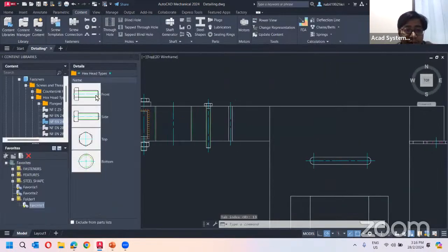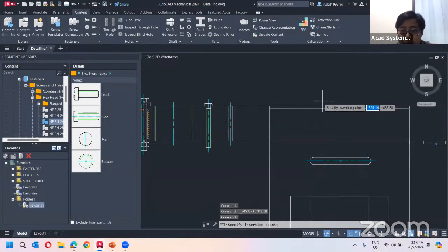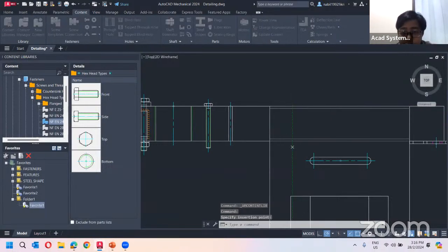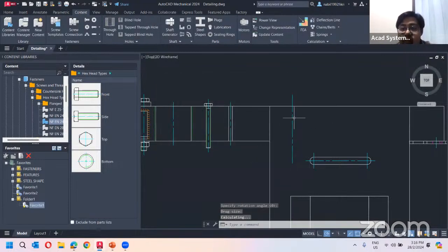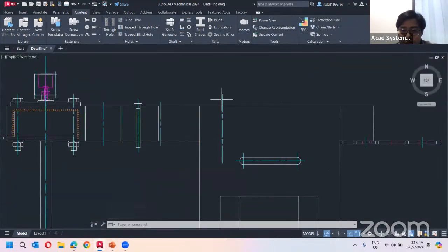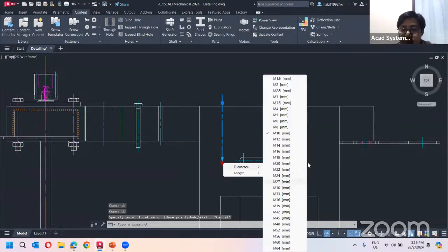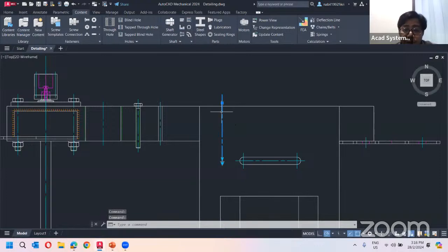And then when I add another type of item from here, you will see it's only showing the center line, the symbol only. But it's not actually just a center line. It has properties inside. So if I hover my mouse, it will show me what item this is. So the content type is standard parts, text head, bolt, and so on. I can click here, I can drop down, I can specify and change the settings, the size of my bolt from here,